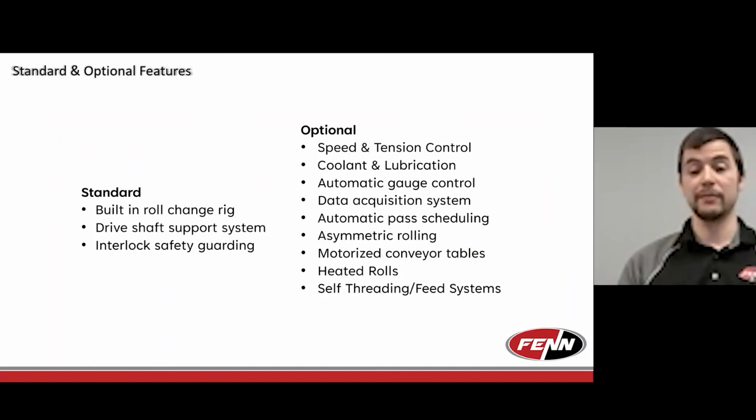And then the only other purpose that I've used heated rolls for is where the concern with thermal expansion is so severe that internally and externally cooling the rolls to control thermal expansion isn't good enough. And we deliberately preheat the rolls up to the point at which they thermally expand so that they won't heat up any further, and instead use heated rolls to do that. So those are the primary purposes that heated rolls are used for, which, I'd say, you most often see on the hot rolling side, mainly as a way of trying to maintain heat in the material.